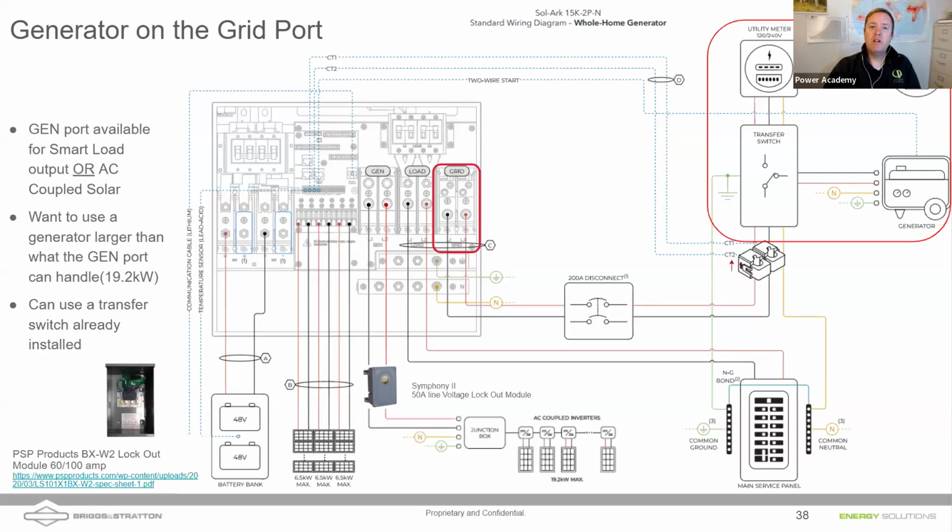but when the Solarc is connected to the grid, it's a grid following. Sorry, and generator. Yeah, or the generator. And as soon as it sees an AC coupled source, it's going to start following that. That's fine for the grid with AC coupled solar because we can backfeed to the grid. But when we have a generator, we don't want to backfeed. So what do we have to do, Nathan, if we're going to have AC coupled solar and a generator?